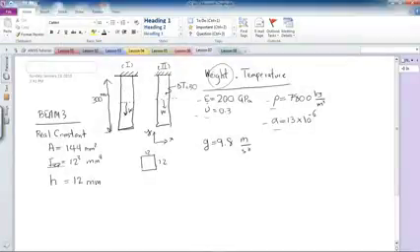The first one was its own weight, and the second one was weight and temperature difference with this cross-section area and the height of 300 millimeters. But when I did the analysis with a beam 3 element in here, and when I represented a 3D representation or model of the analysis, we saw that conservation of mass or volume was not taken into account in the analysis.